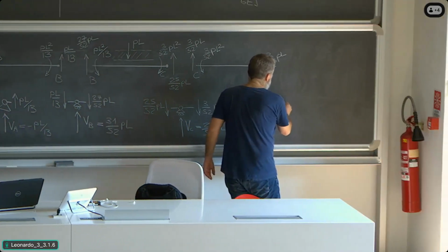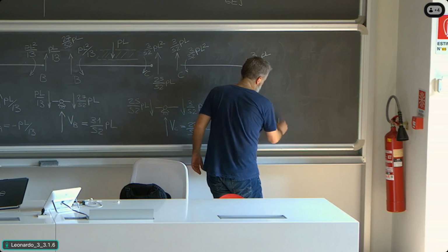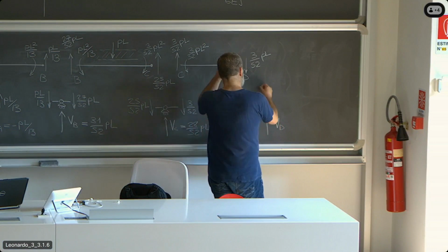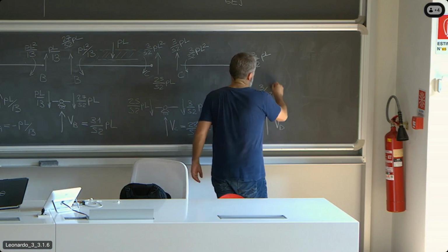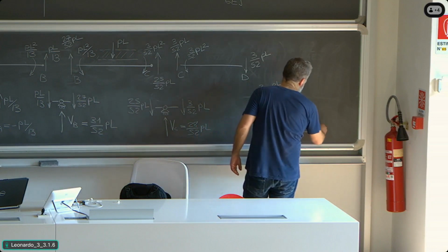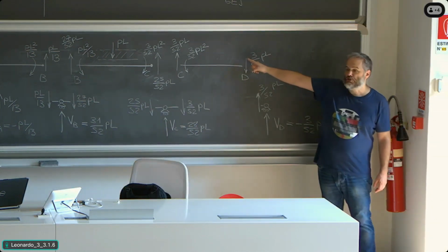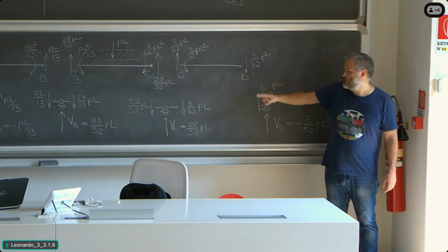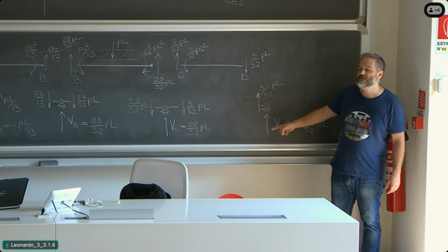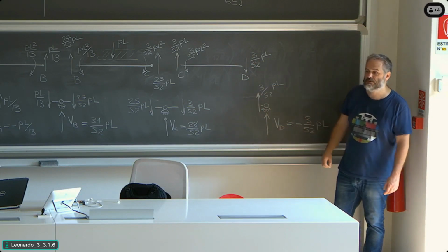And then point D. Minus 3/52, as in the situation of point A. So, the shear force on the beam is downwards, which means it is reversed on the support, which means if I assume the reaction force is upwards, it will have a negative sign, which is downwards. Okay?